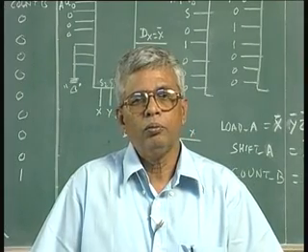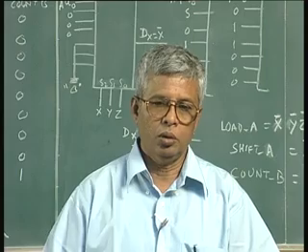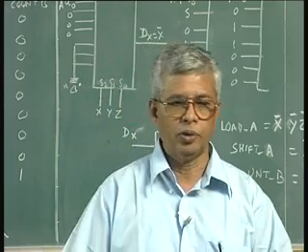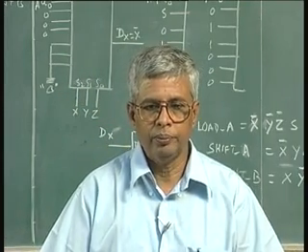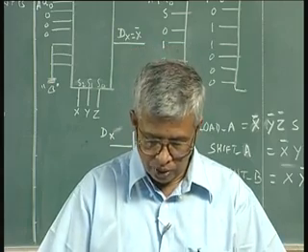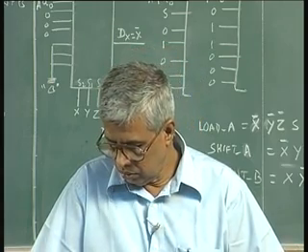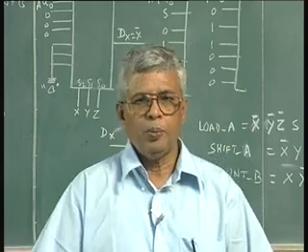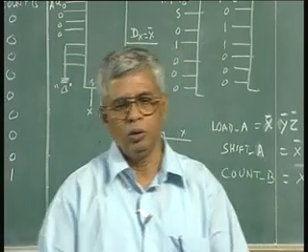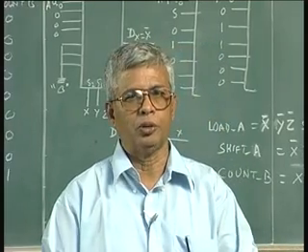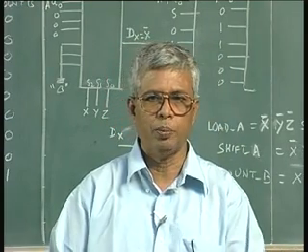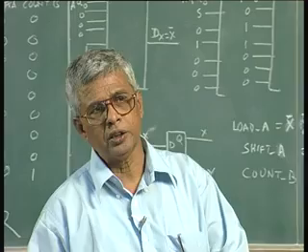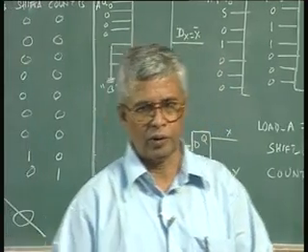And then we took examples of simple code pattern generators, and how to identify a pattern from a series of bits, sequence detectors as they are called. Then we talked about other, slightly more involved systems like a traffic light controller. We reduced the problem to a state graph and showed how to do a state graph implementation using different approaches: multiplexer based, PLA based, PAL based, and also using registers and counters instead of only flip flops as sequential building blocks.